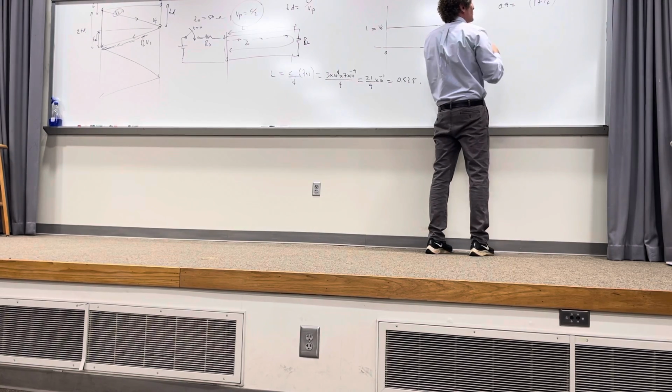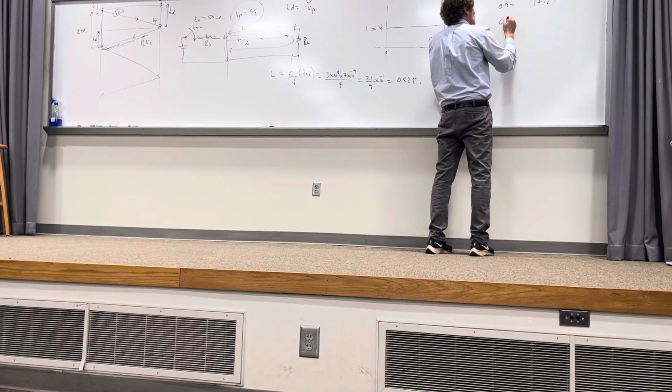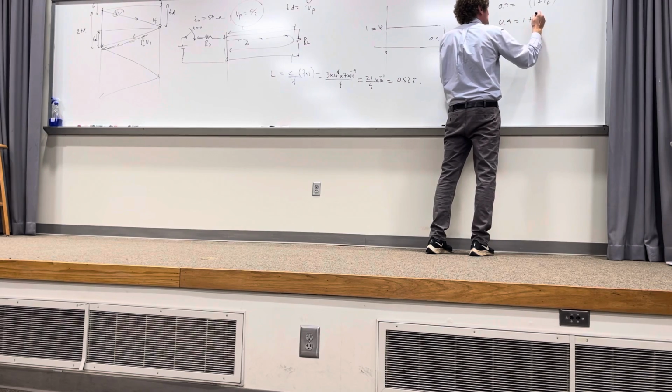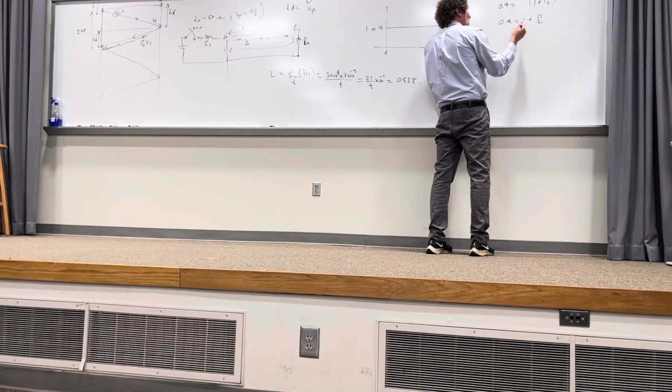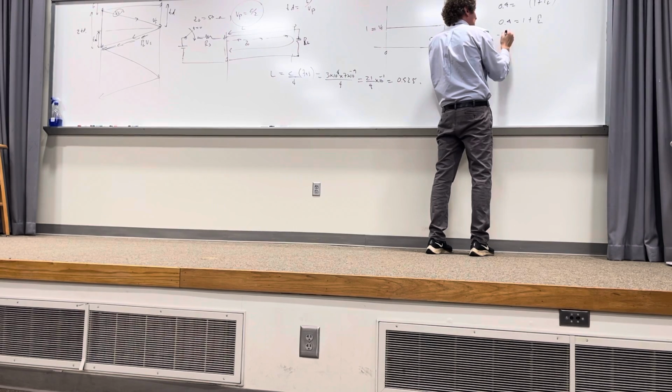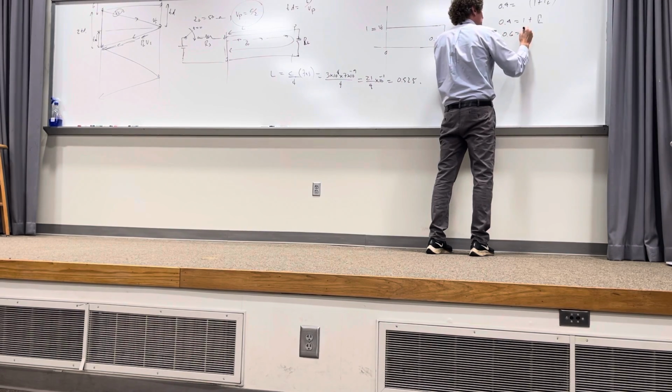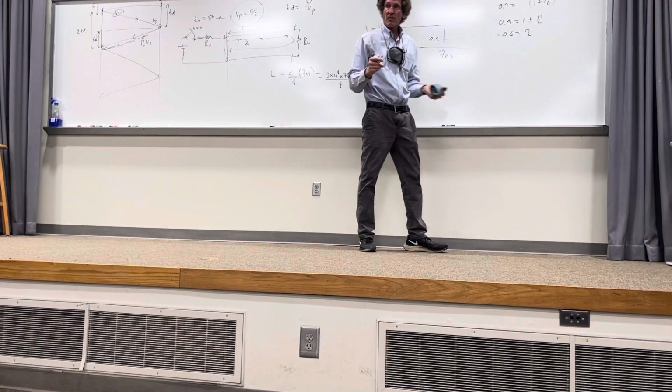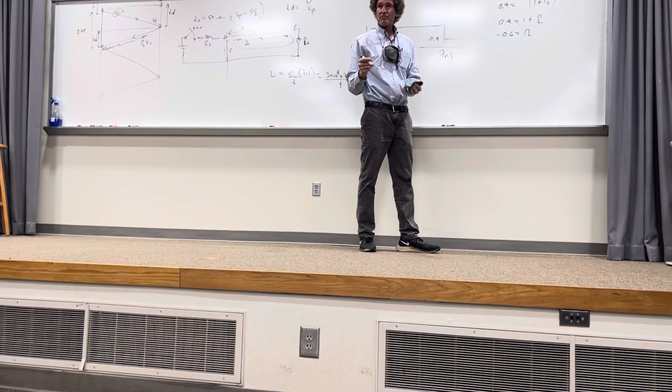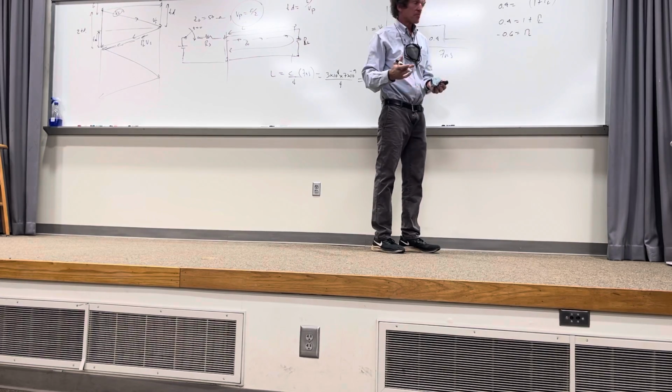And now I can see what? I've got 0.4 is equal to 1 plus the reflection coefficient at the load. Or if I take -1 to this side, I have -0.6 is equal to the reflection coefficient at the load. Do y'all follow me? Y'all agree with this? All right, now what is the reflection coefficient at the load defined as?